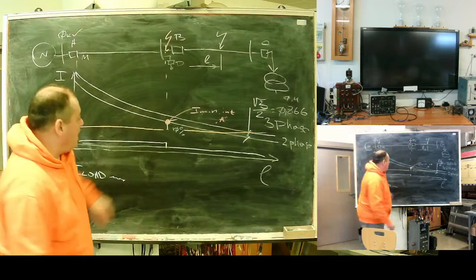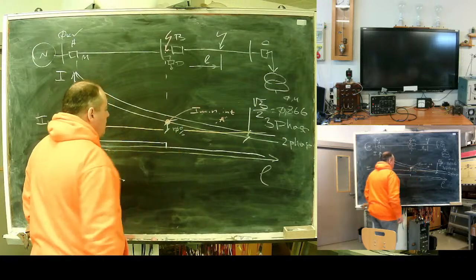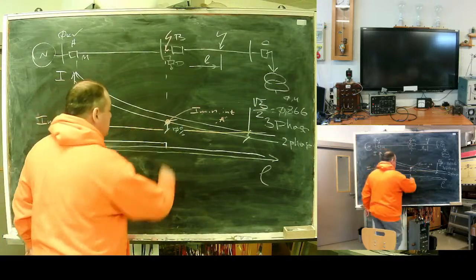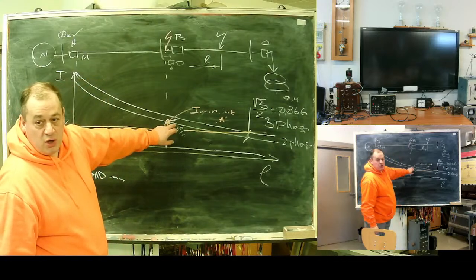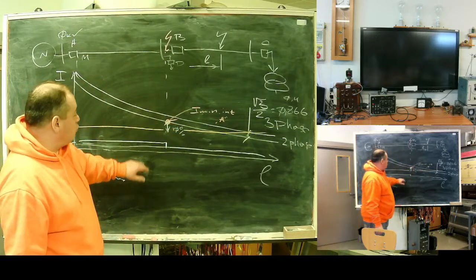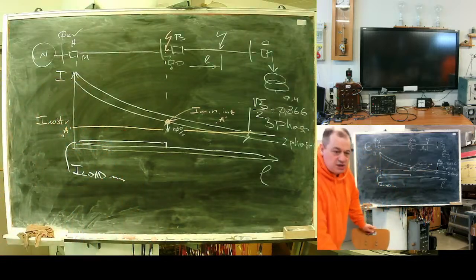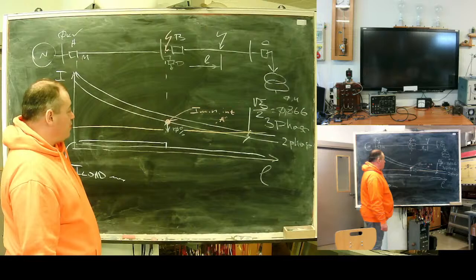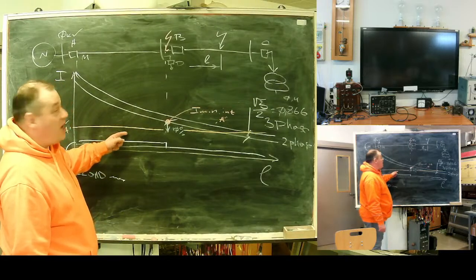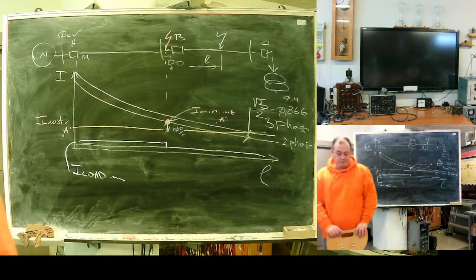And here I took a gap of 10% from the minimal internal fault current to get this nice orange line. This orange line is a first approach for the trip current of this protection A.